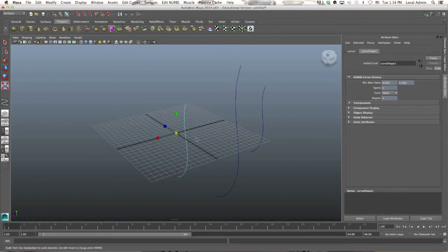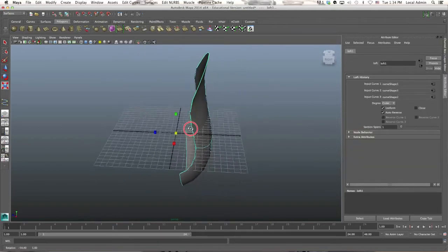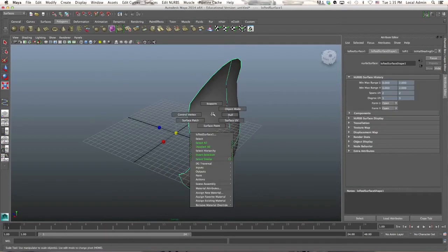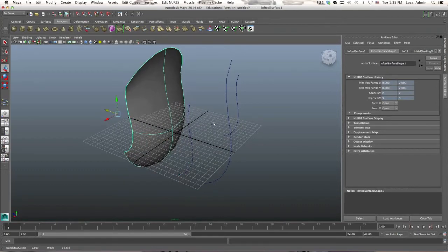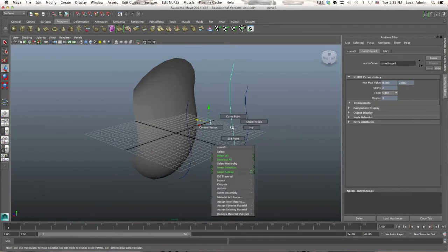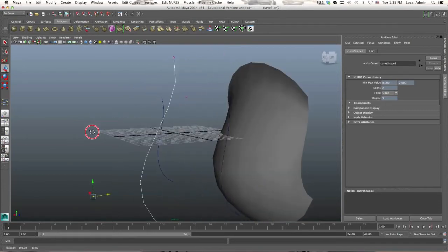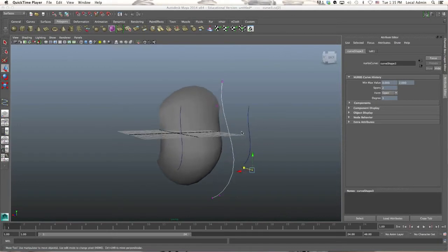Then I'm going to select these curves in order, and then hit Surfaces Loft, and you see it will draw a curved shell between all of those. And I can go to object mode and move that here and adjust it after the fact as well. Under control vertex, I may want it to bulge out a little bit more there. And you can use that to sculpt car parts or anything. I'll undo that now. Let's go back to object mode and delete all that.